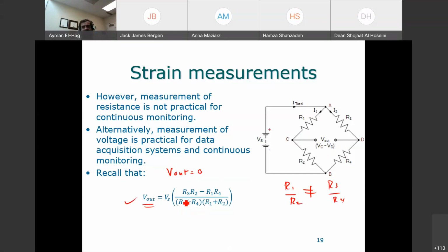Second thing, which is very important, is how you measure the resistance here practically. If you want to measure the resistance practically, you have to connect something here in parallel with the resistance. This is your ohm meter. But this resistance is not the value of this resistance only. It's the value of this R in combination with all other resistors, because they are in series and in parallel.